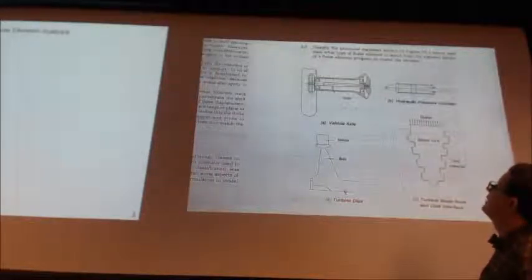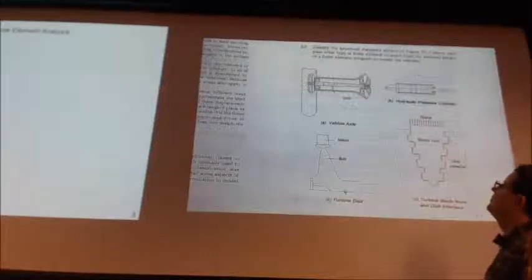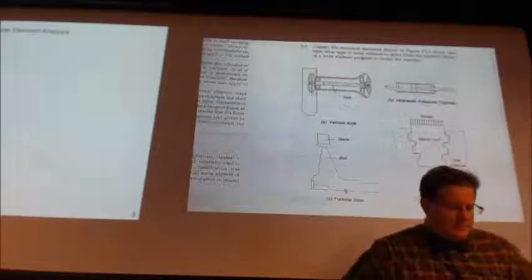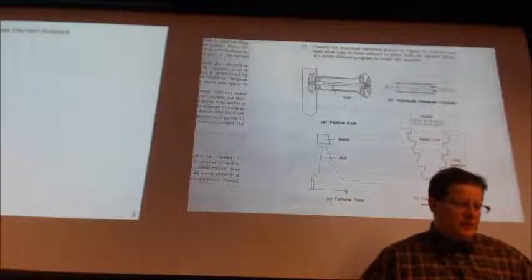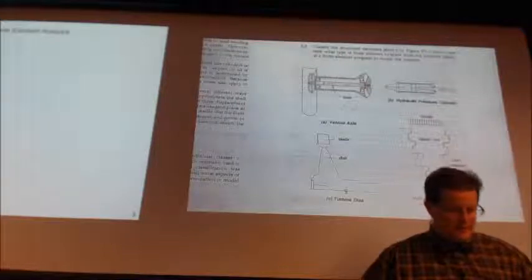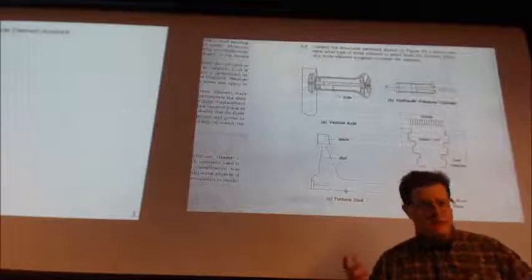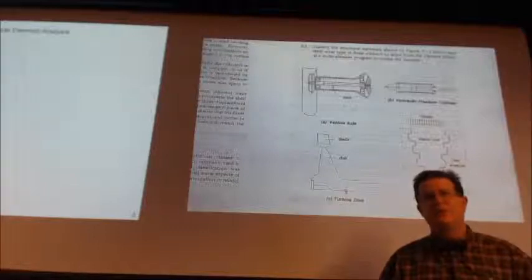Well, it is in a housing, I guess. And you should have bearings at each end. Could you use the axisymmetric solid one? Yes, since it does have... I was thinking about a beam, but I was forgetting about, you've got bearings at each end, and once you get past the bearing, out at the end that's holding the brake and the wheel itself, you could treat that as a beam.